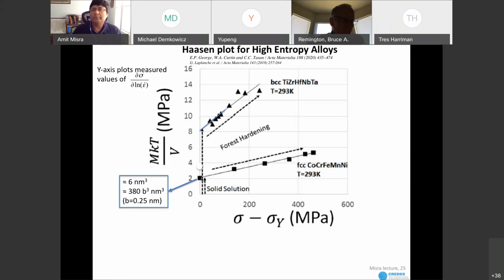Right. But actually my question is that for rate-dependent material, usually from the constitutive relation, we have the onset of plastic strain since the beginning of the whole deformation process. So it's not easy to really distinguish the onset of plastic deformation. For this kind of material, usually in a constitutive relation, we do not have the concept of yield. We have the concept of reference stress, but usually we cannot see the onset of a very noticeable plastic flow for this viscoplastic material. So yeah, that's the question. But I guess you are talking about how to represent it in a constitutive equation.